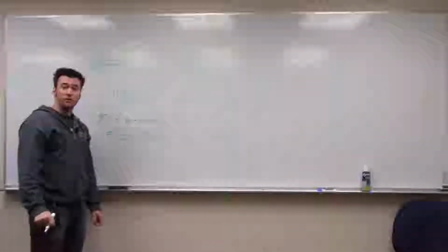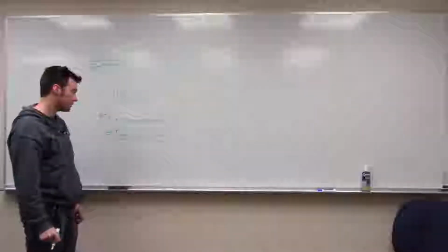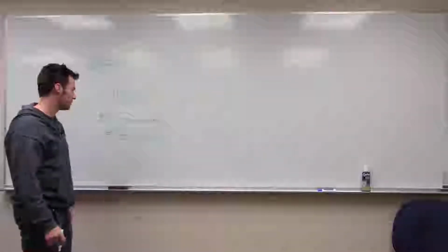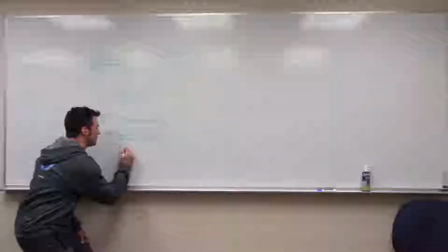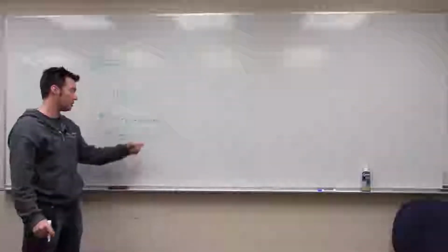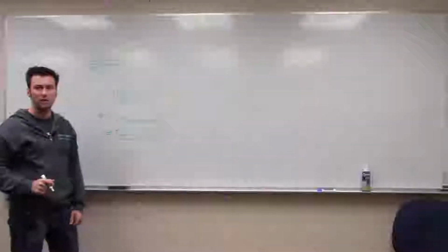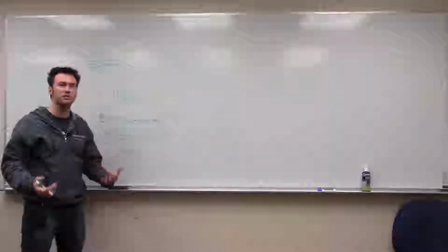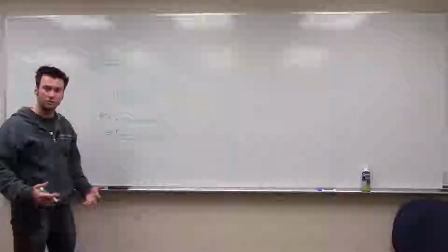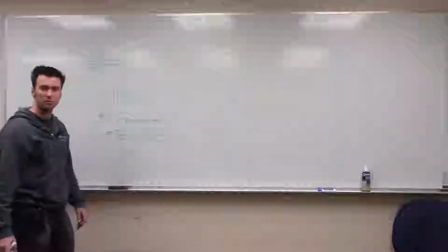Next step is to solve this equation of motion, and this is a linear second order differential equation. Let's analyze that. So we said it's linear. That just means that the variable itself, x dot, x double dot, don't appear squared or inside of a sine function. It's just the variable or the derivative itself lying out there in the equation, not multiplied times another one of them. It's only multiplied by constants.